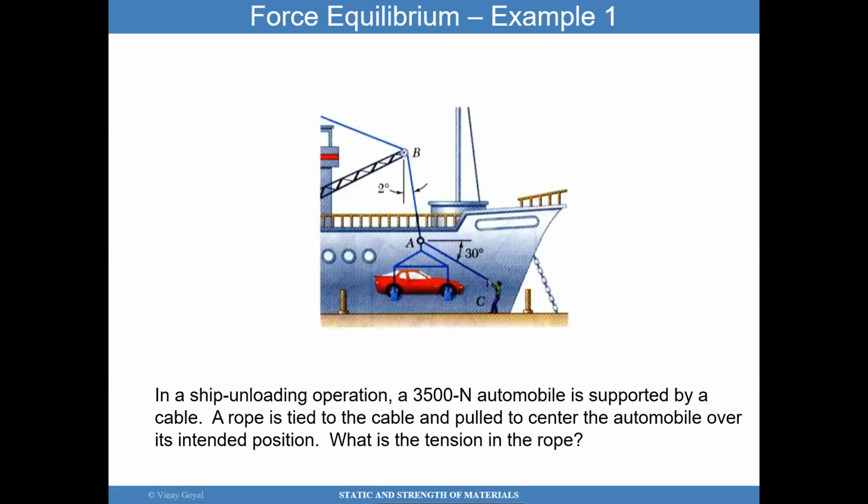So here's a force equilibrium example one. I have a ship unloading operation situation. I have an auto that has 3,500 newton weight and is supported by this cable system. A rope is tied to the cable and pulled to the center to the intended position. And the question is, what is the tension of this rope?